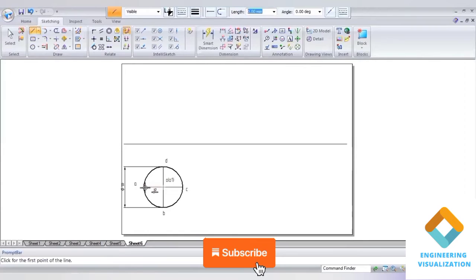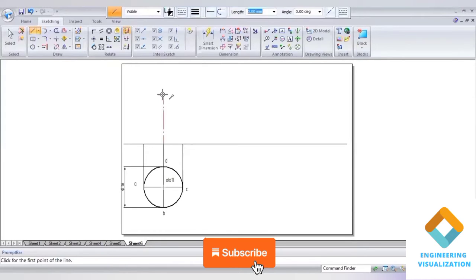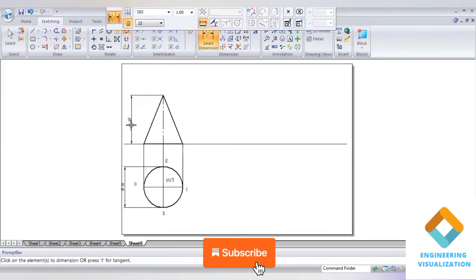Draw the projection lines upward to complete the front view. Axis length here I'll be considering 60 mm. Axis height of 60. Show the dimensions.